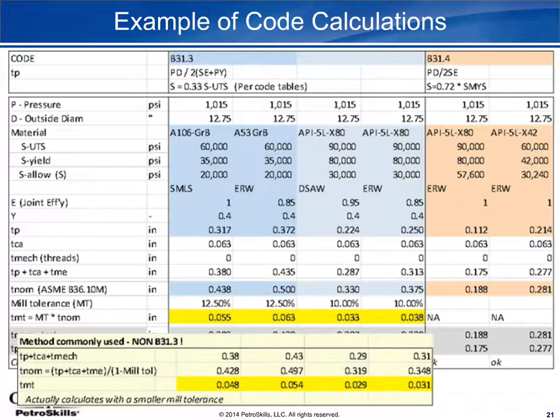There is no short answer to this question. To answer it completely, we would have to go back to B31.3, do a formal analysis, and work out, is that too cold? So in a major project, we would look at the construction temperature and run a few sensitivity studies, run some basic Caesar runs to work out, well, is this going to be acceptable at this size or this size?